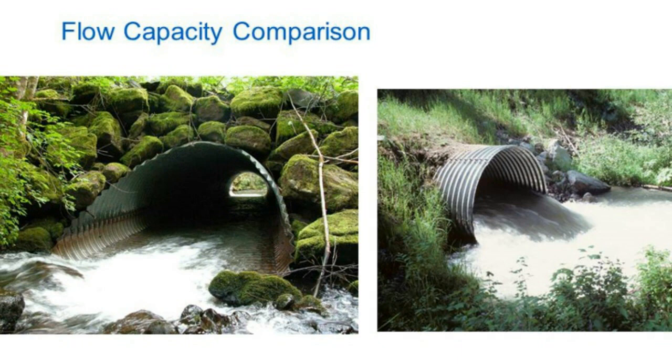Further on in the presentation, we'll see some examples of ways that you can increase cross-sectional area to be closer to the host pipe's original condition, should it be required, and ways to slow down the flow through the barrel if necessary, as this can cause problems at the outlet and also if the water is moving too fast through the pipe.